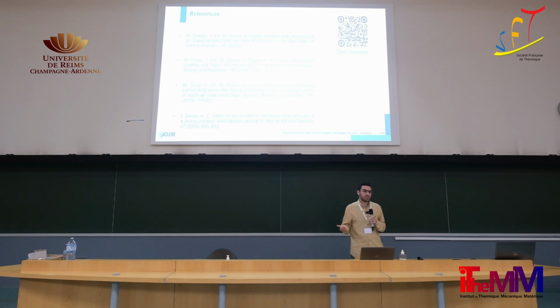But there are other systems using water. It could be for other things. So it's a different type. The depth varies between 0.7 meter and 1.2 meters. And the variation is to collect any water that can condensate on the pipe. So that's why we have the variation.